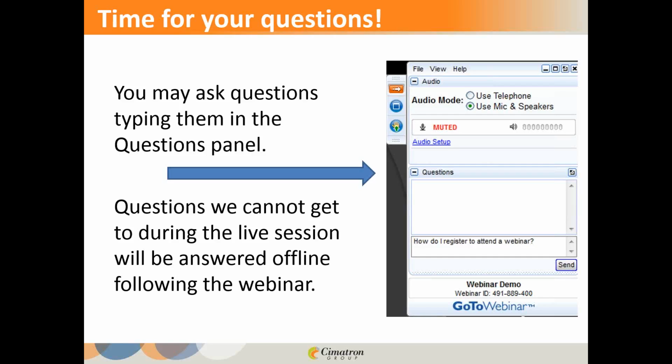Right. And if you do a model for one material and the material changes midway through the program, how complicated is that to change the material properties? In that case, you just tell it to resimulate using a different material. Or it could also be changing the thickness, changing your gauge size. That would also affect it. So you can make those adjustments, get your simulation to see what the part's going to look like or how the blank size may change, and then continue on from there. That may mean adjusting some of your punch sizes, or it might mean, like the example we looked at, maybe changing my binder a bit, making it bigger or smaller depending upon the case.